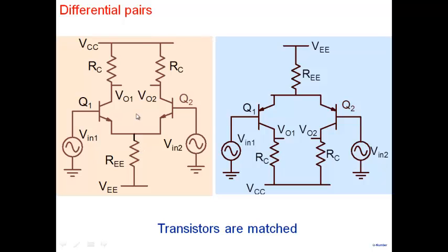And remember, when you're building things on an IC, you don't want to use resistors. You want to minimize resistors because they occupy a large area. So as much as possible, take a resistor out and replace it by a transistor. So if this one is there just for biasing, I can take this resistor out and replace it by a transistor also. All that you require is that I should have a current source here. And this current source will supply current to here and here. So I can take this out and replace it by a transistor and bias it in saturation, in the active region. So we can imagine now how our differential pair is going to evolve. I'll replace it by a transistor here. I can replace it by a transistor here, replace a transistor here. I can replace it by two transistors here, a cascode connection here, and that's how differential pairs will change.